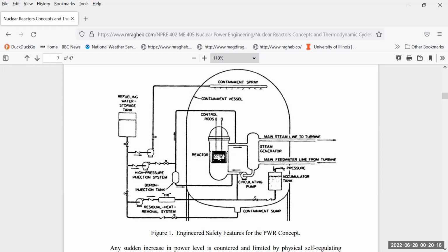And something interesting about nuclear power plants that differs them from existing, say, fossil fuel power plants or coal power plants is that even if you shut down the chain reaction in the core, you would reduce the power from 3,000 megawatt thermal generated to still a residual power, or what we call the residual heat or the decay heat, from the radioactivity of the fission products, still emitting beta particles, electrons, and gamma radiation. You find yourself with an 8 megawatt out of 3,000 megawatt still being generated for about a 24-hour period.